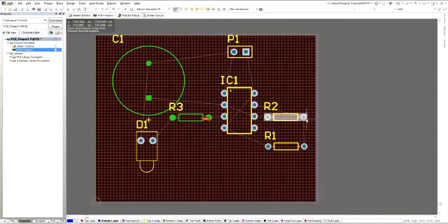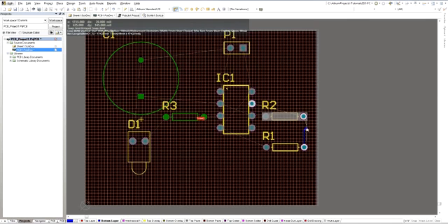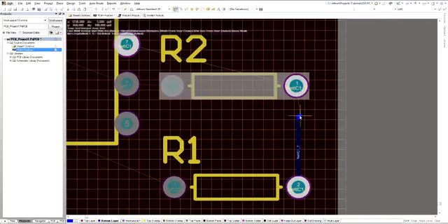You're gonna start placing the track, and you simply click where you want to have it. And to change between different modes, just as we did before, this is shift space, and you can select, as you can see, there's various modes that you can use for your tracks. So I prefer going with this one.